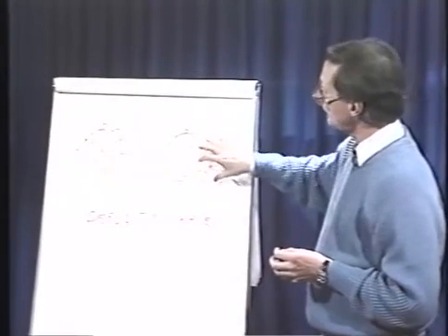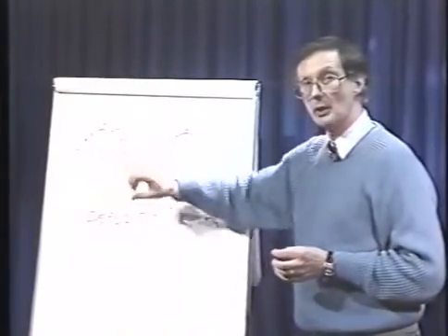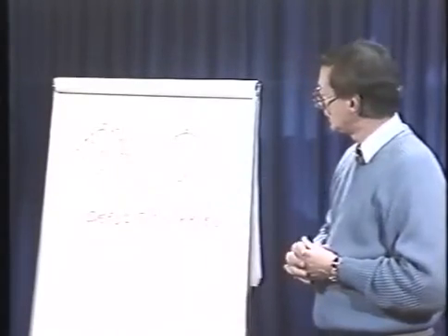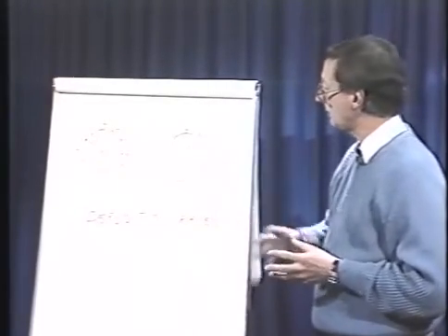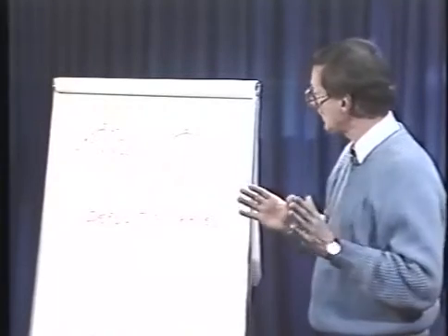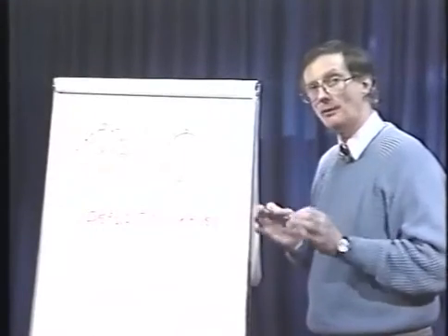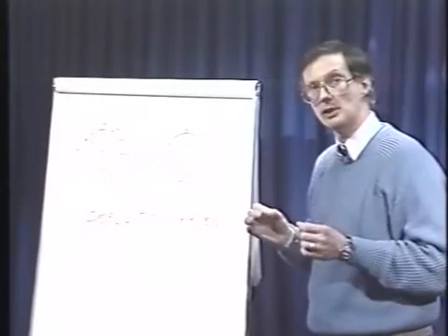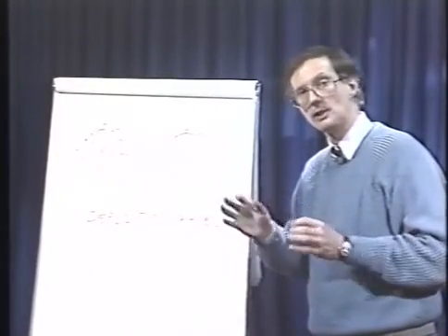Already you are 50% more than you will attain with an 035 wire. Traditionally, again, we do not go too high with an 045 because of the turbulence, but 14 to 15 pounds an hour is readily attained with an 045. This is the reason the 045 wire should be utilized on all applications over 3/16 of an inch.